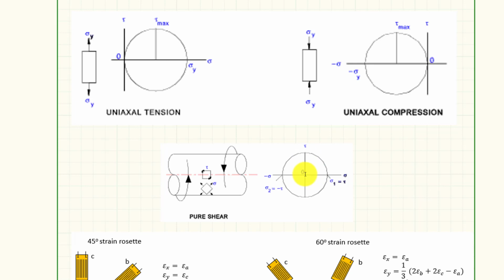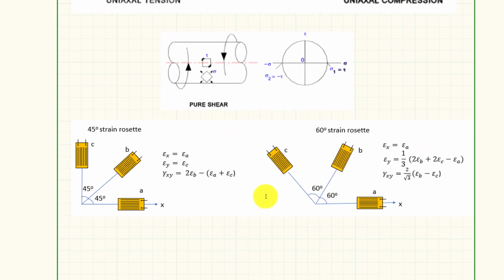Now in real life, in our application, we might see it adjusted off a little bit. That's okay, because the way we're loading it, there could be slight loading on there, but we're still going to calculate those, and the way we do it with Mohr circle, it's going to take in those odd stresses that maybe aren't just pure shear or torsion. It's going to take that into effect with our values doing this Mohr circle.